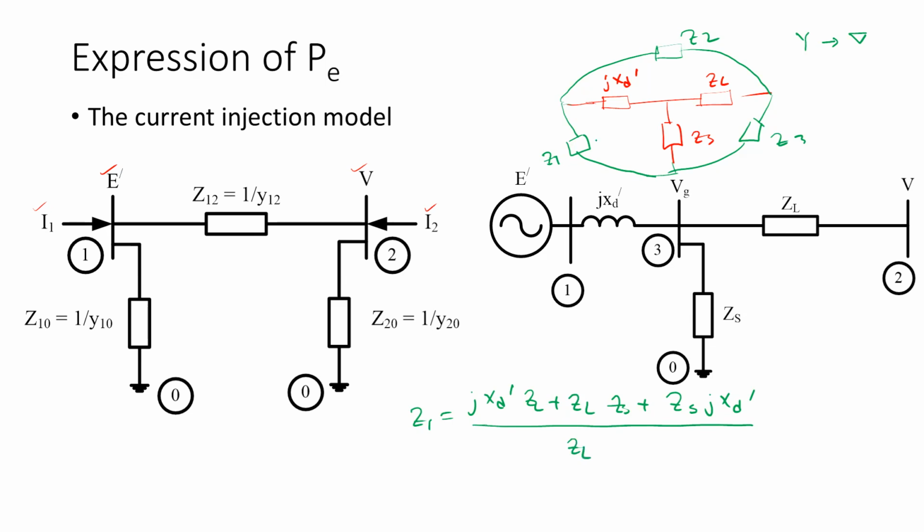So what we have when we are deriving for this one, the opposite Y connection becomes the denominator and every other combination comes as a pair product. Fine. So this is how we get Z1. Similarly, you can have Z2. Similarly, you can have Z3. So that is exactly what they got. They just named it in a bit better way so that it's easier to understand.